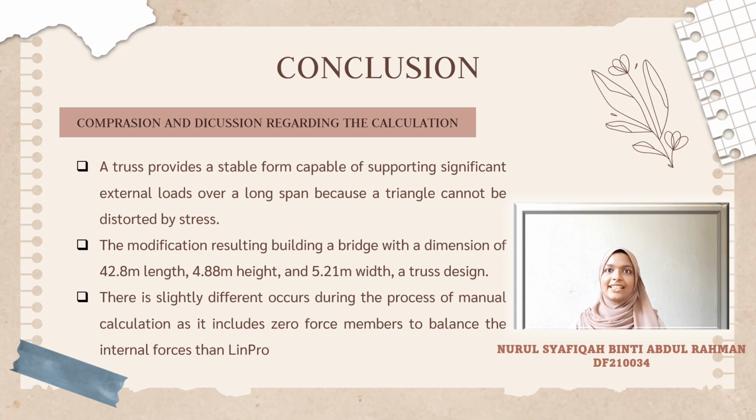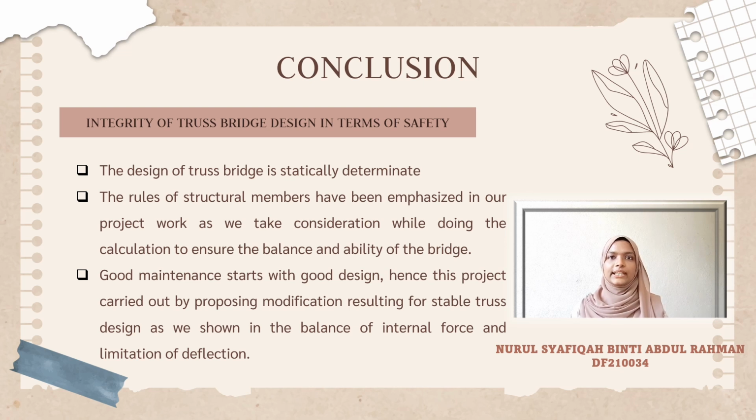In the truss design, the comparison between LINPRO software data and manual calculation shows the reaction on support and internal forces. There is a slight difference during the manual calculation as it includes zero force members to balance the internal forces. However, we still could use both results from LINPRO and manual calculation for operation purposes by choosing one of them. As for the integrity of our truss bridge design in terms of safety, this design of truss bridge is statically determinate.